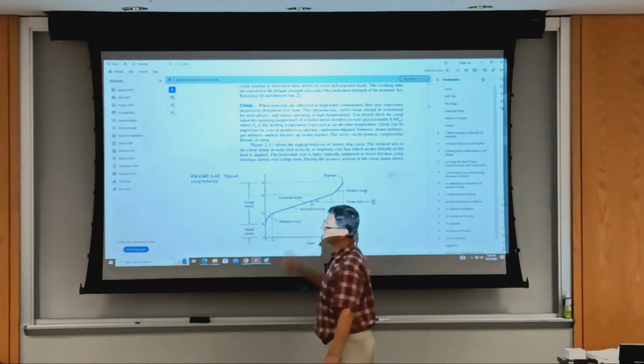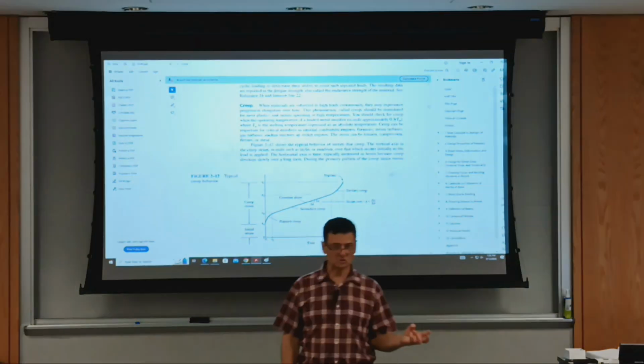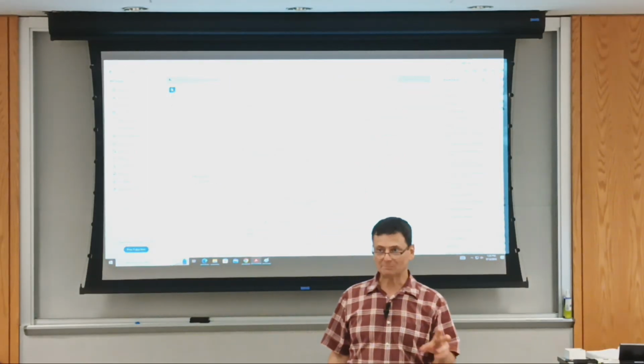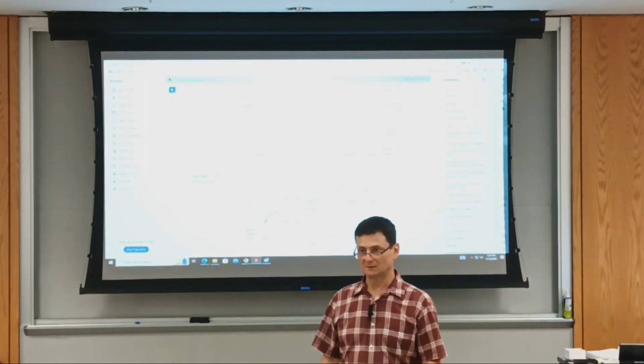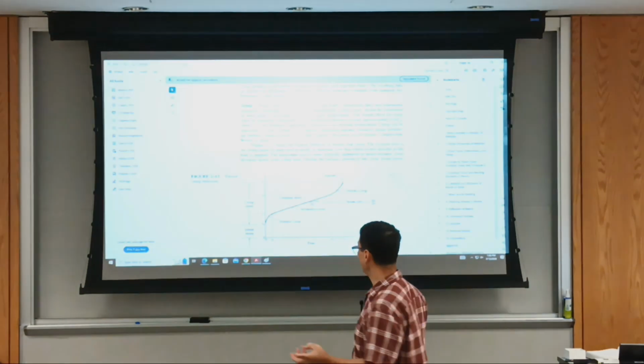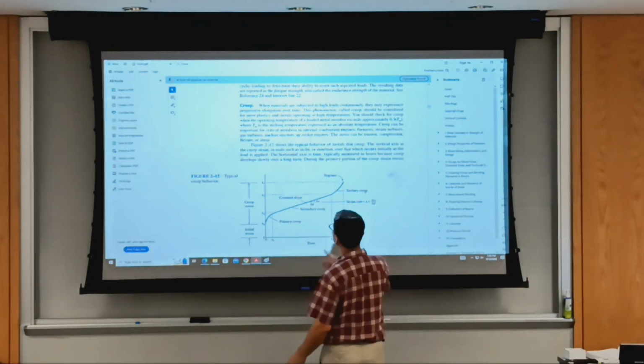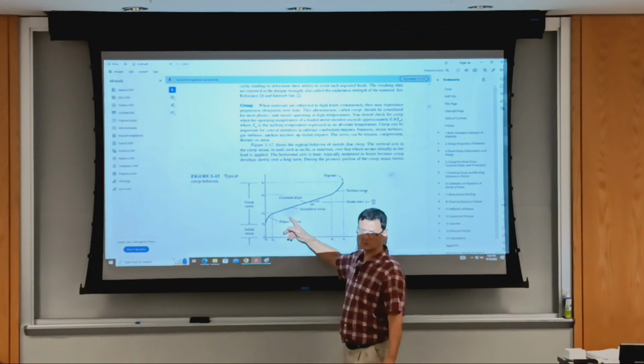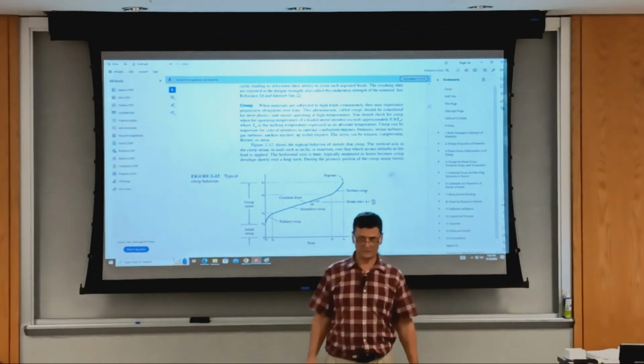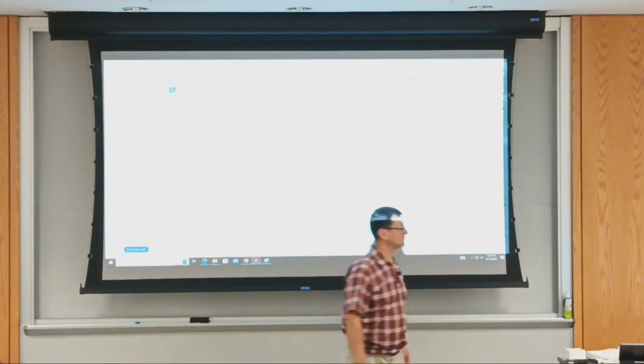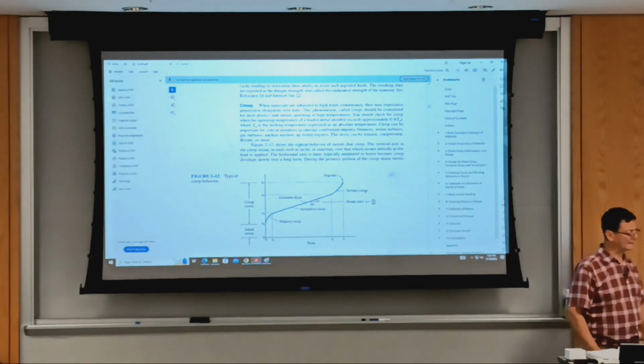So something to consider. For that reason, gas turbine blades are sometimes made in a single crystal, so that they hold very close to their melting temperature. They hold their strength, they hold their geometry. Although bad things can happen.